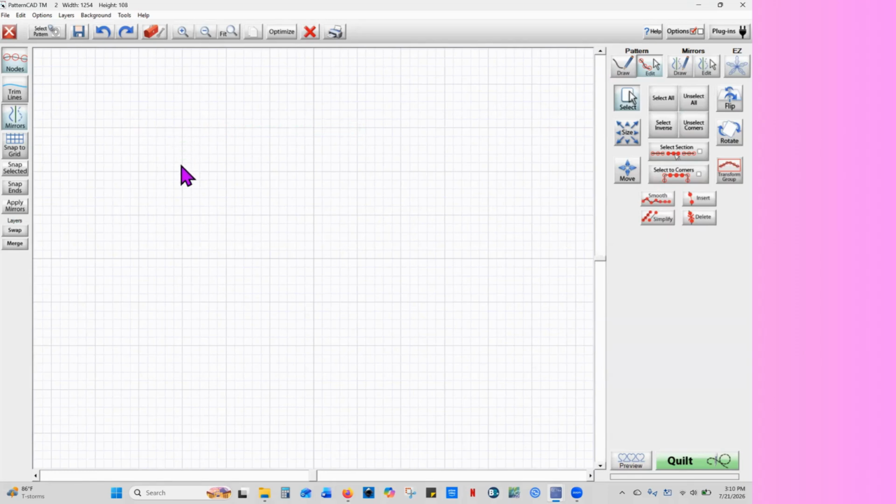So I'm going to left click. And as you can see, this is a circular shape. You don't have to make a circle, but it has 1 apex. I can't drag it this way or that way like I did with a spline. I can only move it like I'm going to make a circle. The handle is going to be exactly in between the 2 endpoints. And so it would make a circle if I wanted to, but it's circular in shape. And I can do these lines separately, or I can select them both and move them at the same time.